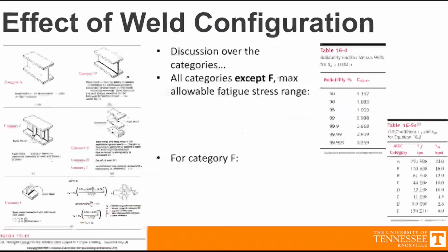So one of the main things that does actually influence fatigue, rather than these knockoff factors, is the configuration of the weld. A group called AISC, the American Institute for Steel Construction, tested a bunch of these different geometries and made a really big table, a section of which you can see here, with different categories of welding geometries.